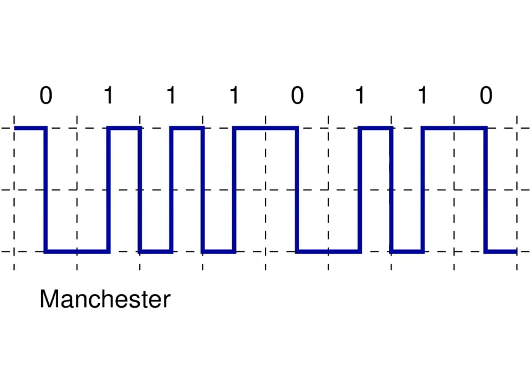That is, to send the same amount of data, our transmitter needs the electronics, the circuitry, to change the signal at a faster rate, which is harder to do. So here we have a higher signaling rate, but the same data rate. Ideally, we'd like to have a high data rate and a low signaling rate. What if we have a long sequence of zeros with Manchester encoding? Will the signal be the one level all the time?